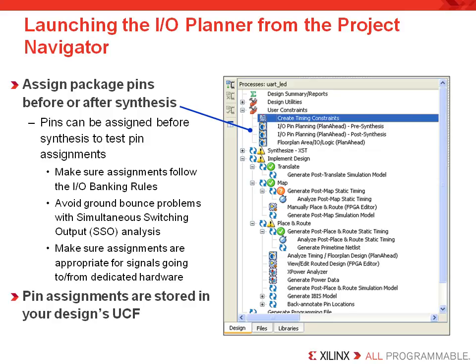Keep in mind that the noise analysis is not a complete ground bounce check because, of course, whether you have a ground bounce problem will depend greatly on the operation of your circuit and if multiple pins will end up transitioning at one time. Remember that the implementation tools also cannot anticipate this kind of problem. Unfortunately, that's always left to the designer to determine for themselves.